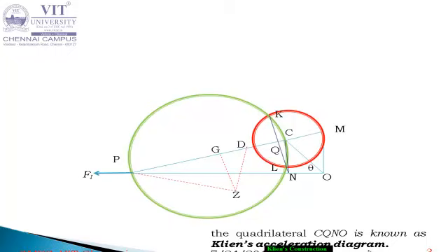So for this position, the second mass is concentrated on D. The entire mass of the connecting rod is not located on the crank pin. The load is concentrated on the point D, and with respect to this point you have to calculate the inertia force.